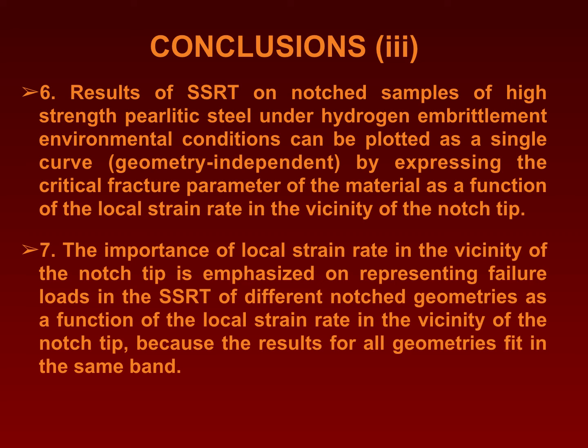And finally, last but not least, 7. The importance of local strain rate in the vicinity of the notch tip is emphasized in representing failure loads in the slow strain rate test of different notch geometries as a function of the local strain rate in the vicinity of the notch tip, or just at the notch tip, or averaged in the vicinity, the notch tip strain rate, because the results for all geometries fit in the same band in this universal curve, geometry independent, triaxiality independent, that represents the kinematic approach, the kinematic fracture criterion for hydrogen embrittlement of pearlitic steel notched samples. That's all.